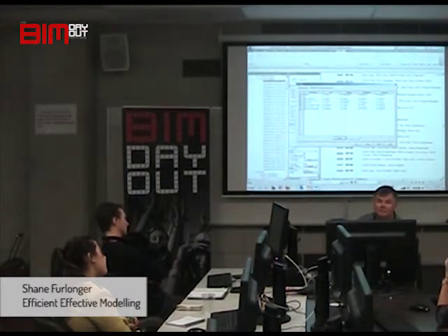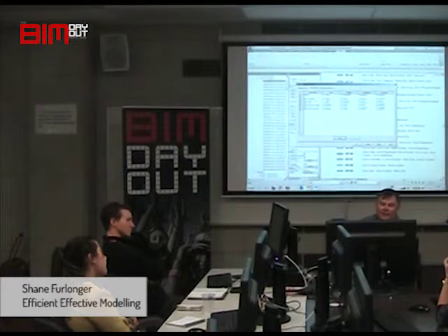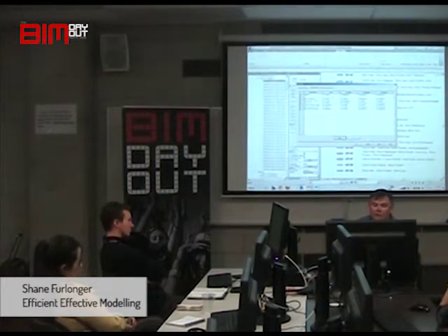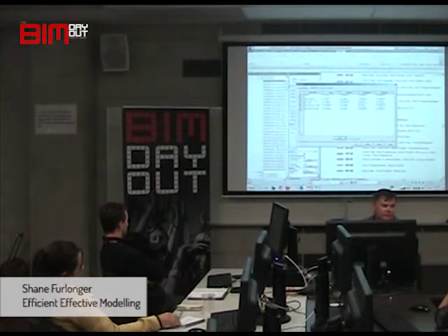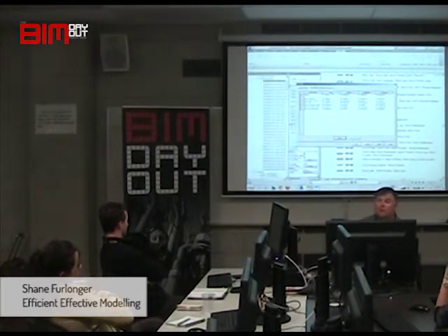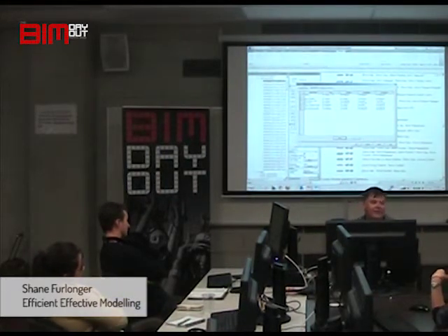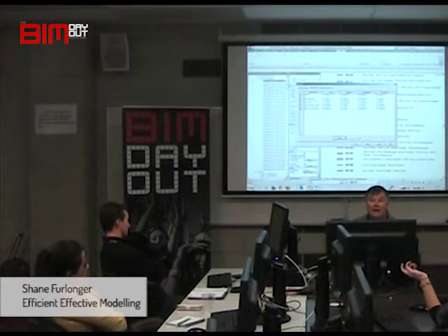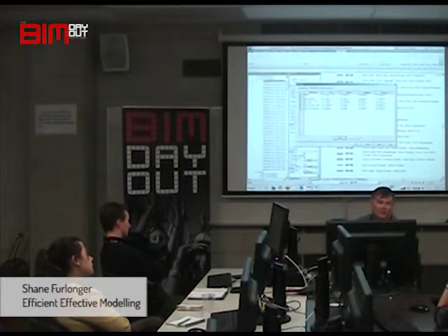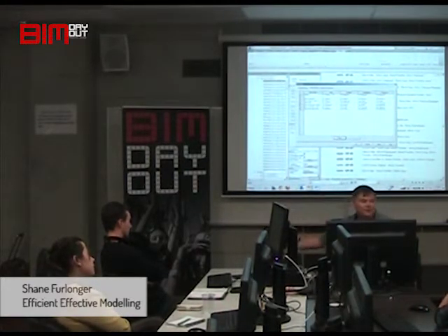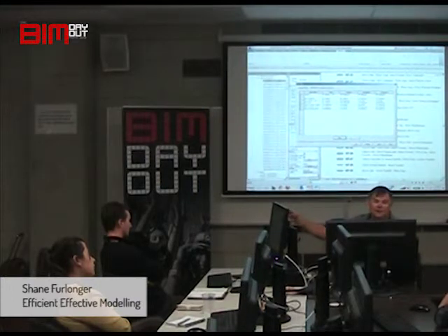Everybody with me? What's new is what's created in the phase you're currently working in. So if you were working in the existing phase and you create something new, it would be new in that phase. And it would exist in any phase after that until it's demolished.